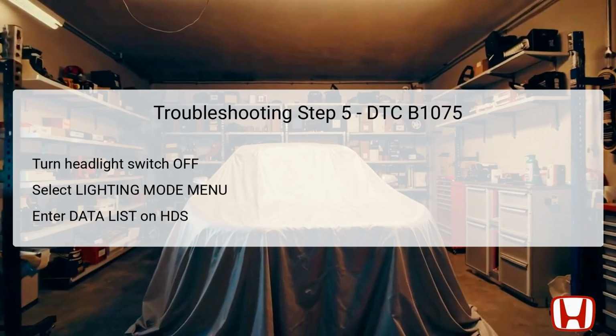Entering the data list allows engineers to examine specific parameters associated with the headlight switch, including its on-off status. This step is vital for determining if the headlight switch is delivering accurate signals as expected. Accurate data from this section helps in verifying whether the faults lie within the switch itself or other connected components.